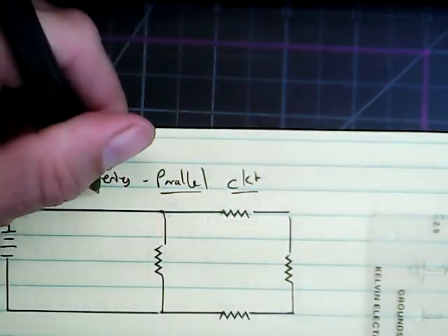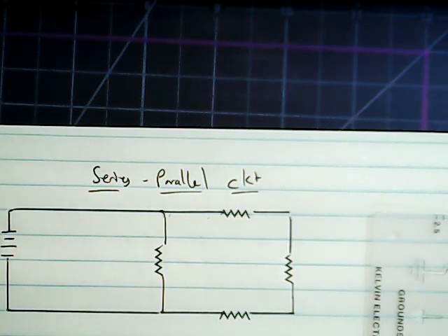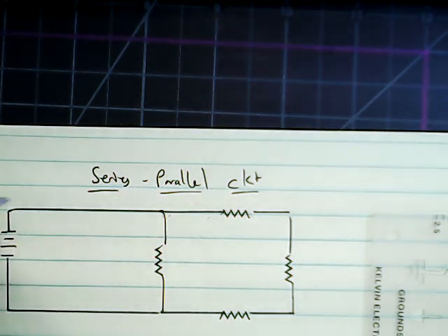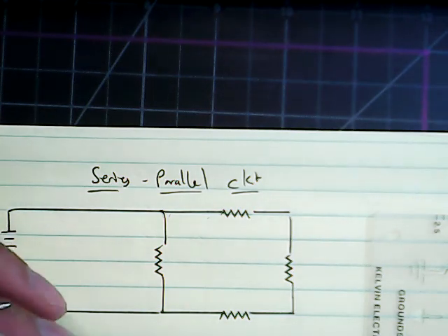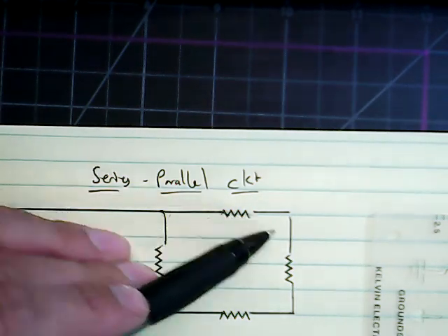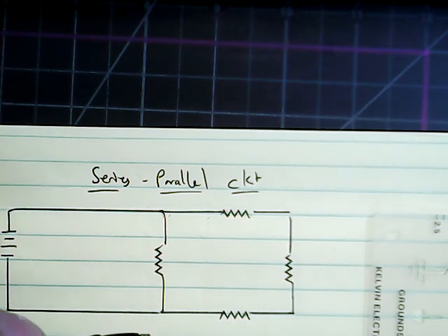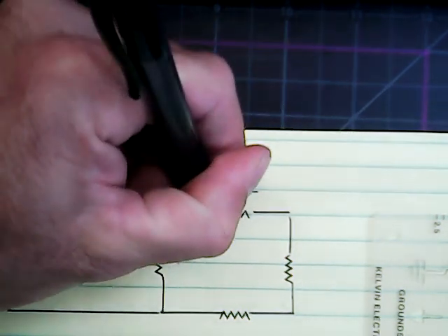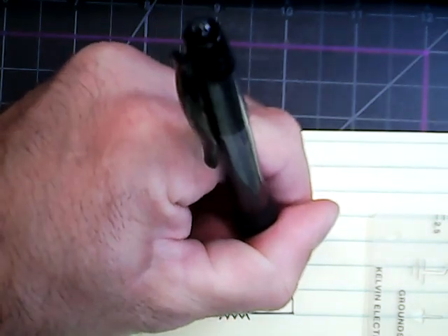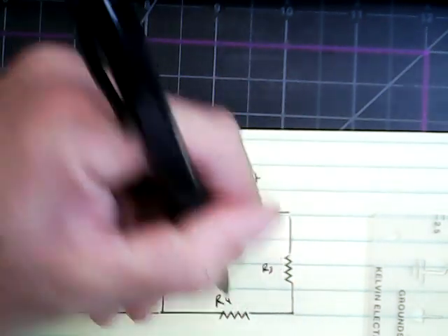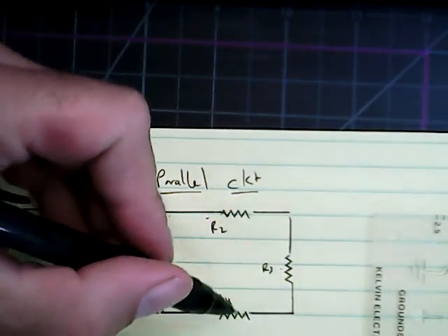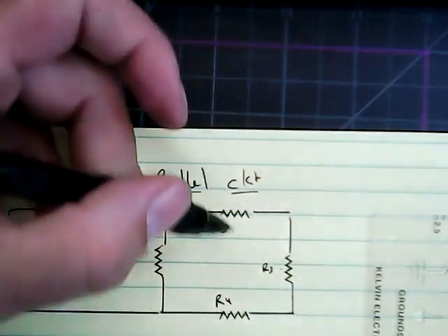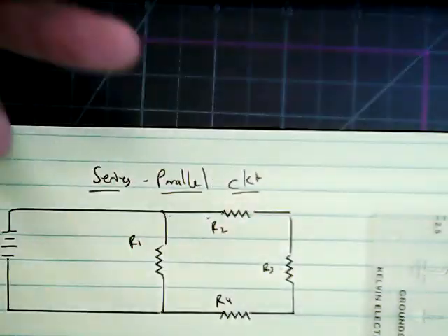the rule of thumb to remember is that when you're working with a series parallel circuit, you keep breaking down the circuit from series to parallel, series to parallel. So we're actually trying to make this series into one resistor. That's what that means, right? So we're going to take the values. I'm just going to give you guys these R1, R2, R3, R4. So R2, R3, and R4, really what we're trying to do is combine these 3 separate loads into one load.